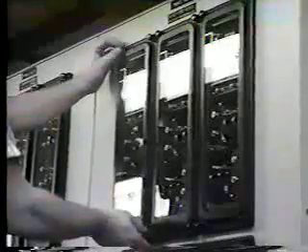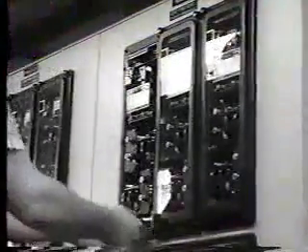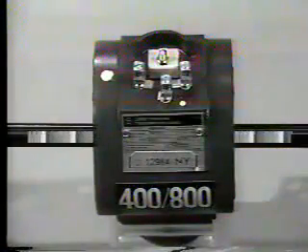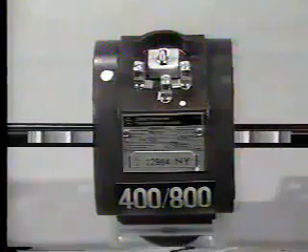When the relay is removed, it is always necessary to open the circuits of the incoming VT and to disconnect DC to the relay. Conversely, the CT connections must be shorted. I'm sure you already know why this is so. If the secondary of a CT is open-circuited, when current is flowing in the primary, a very high voltage would arise across the secondary terminals.